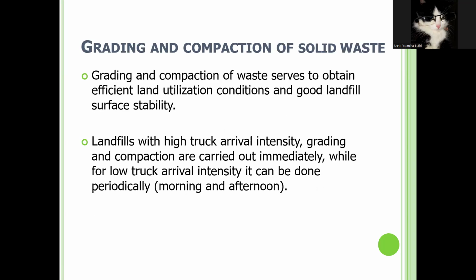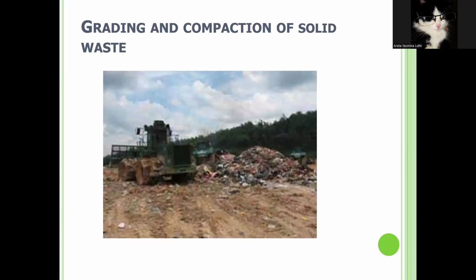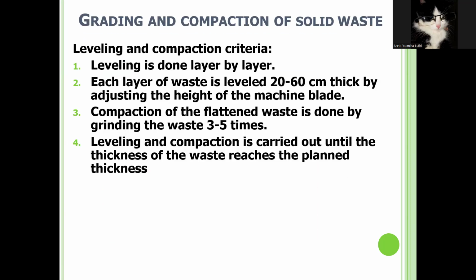And also for the grading and compaction of solid waste, the grading and compaction of waste serves to obtain efficient land utilization conditions and good landfill surface stability. And for landfills with high truck arrival intensity, grading and compaction are carried out immediately, while for low truck arrival intensity, it can be done periodically, which is morning and afternoon. And this is the grading and compaction of solid waste using the heavy equipment.